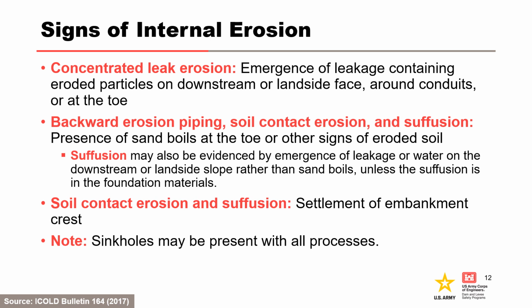For concentrated leak erosion, emergence of leakage containing eroded particles can occur on the downstream or landside face, around conduits, or at the downstream toe. For backward erosion piping, soil contact erosion, and suffusion, sand boils can occur at the downstream toe, or there may be other signs of eroded soil. Suffusion may also be evidenced by emergence of leakage or water on the downstream or landside slope rather than sand boils, unless the suffusion is in the foundation materials.